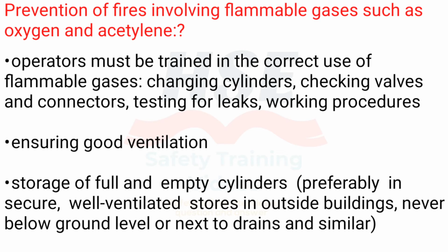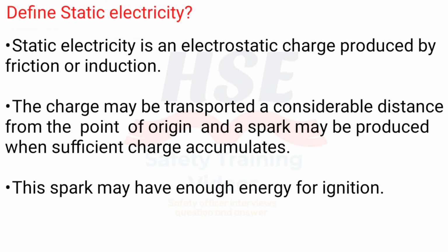Operators must be trained in the correct use of flammable gases, changing cylinders, checking valves and connectors, testing for leaks, working procedures, ensuring good ventilation. Storage of full and empty cylinders, preferably in secure, well-ventilated stores and outside buildings, never below ground level or next to drains and similar.